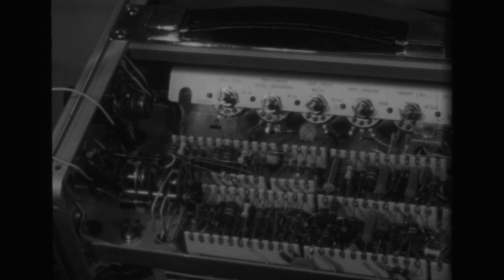Now connect the volt-ohm-meter leads to the 4.7K plate load resistors of the trigger amplifier tube. These resistors are the third and fourth resistor back on the ceramic strips, the inboard ceramic strips. So we make a connection to this resistor, and we make a connection to this resistor.